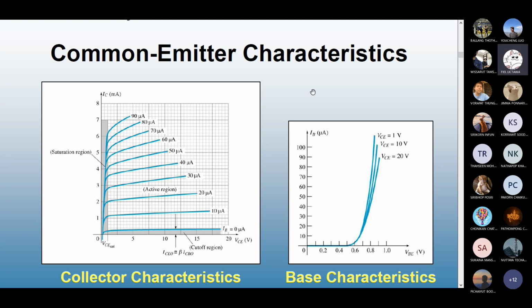Silicon. It is silicon because the forward bias voltage of a silicon diode or transistor is 0.7. And throughout this course, we only assume silicon transistor. I never asked any problem with other types of BJT. Also, I didn't see it in the textbook. So you are clear now, at 0.7 volt, you're going to see some current flowing.